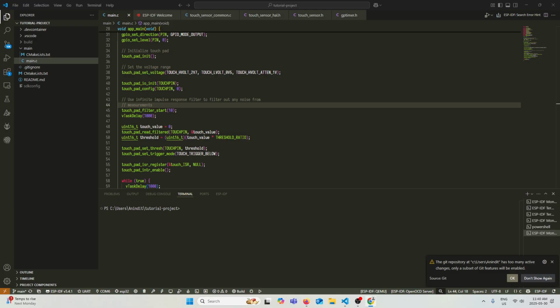This style of ADC is great for how fast and efficient it can convert the signals due to its parallel processing. However, given the large number of comparators needed, and since each bit requires its own output pin, chips can quickly become large and expensive to manufacture. To solve the problem of requiring an output pin for each bit, rather than having numerous parallel outputs, many ADCs run the output signal through a shift register, which then sends serial data out a single output pin.